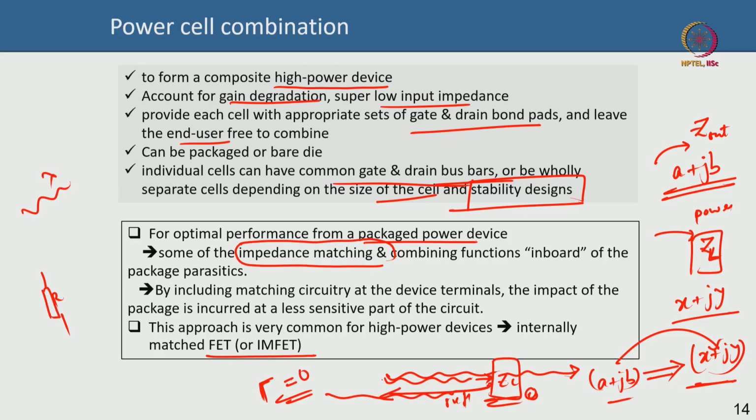So at that kind of frequencies you have to use a transmission line, T line. Transmission line basically is a metallic line on the board. You have a PCB or a Rogers substrate or some kind of a board, on that you have these metallic lines that you can print. The width of the line, the dimension, the angle, the taper, etc., they will all matter.